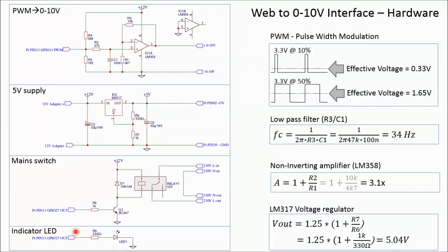Then there is an LED connected to the GPIO 17. This one will be blinking, not only because blinking LEDs are cool, but also to have an indication that your Raspberry Pi is operating and the Node-RED program has started running.